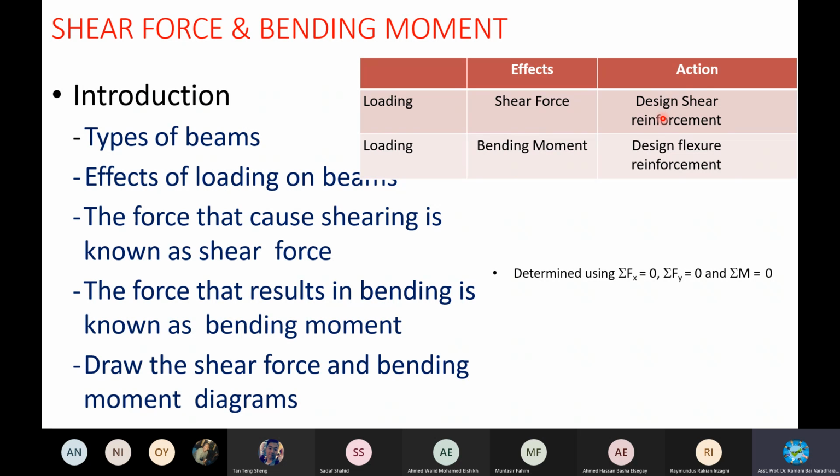Accordingly, as an engineer, you design the response to the overcoming load by designing shear reinforcement. All the ribs, all the links that connect the reinforcement. Later you will study this shear reinforcement. It is the covering applied like rings. I will show it later; it is not the main concern of this study. But for shear reinforcement, the rods are provided and bound by rings at some spacing.